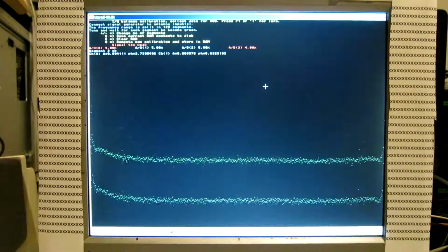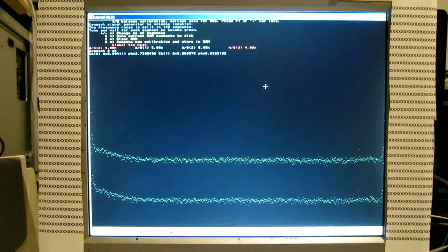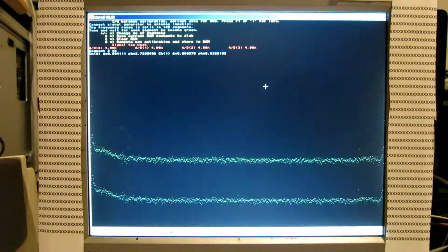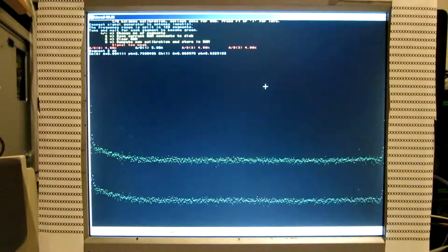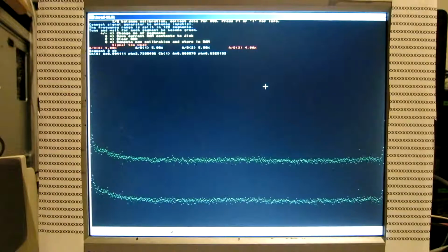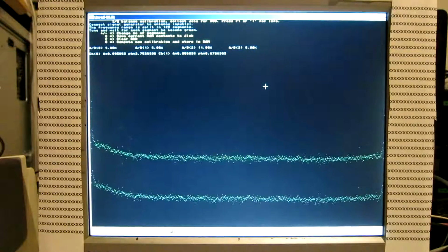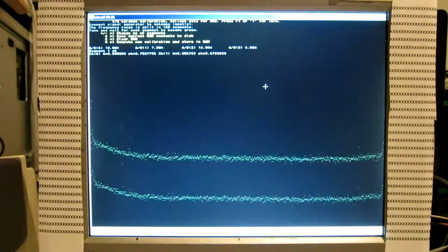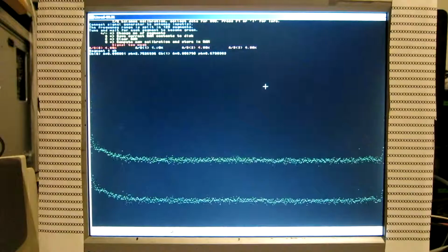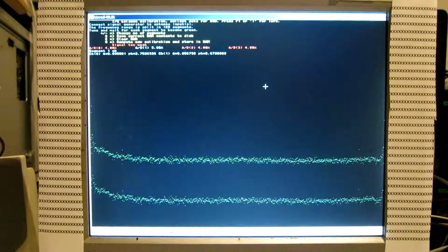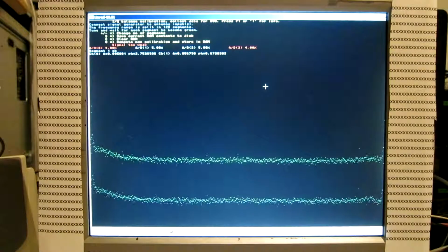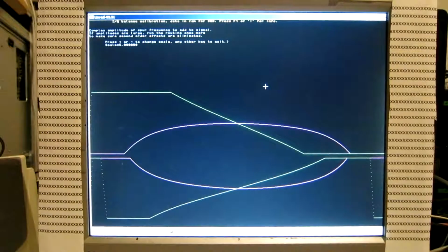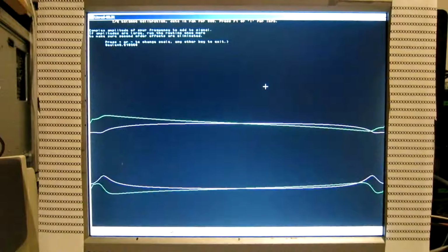At the passband edge, the signal might become too weak. It's now minus 13 dBm. I go up a little bit to minus 5 dBm, say. And then we get that point as well. And now compute new calibration and store it in RAM. That's U as usual. And have a look at it. I press minus so we can see.